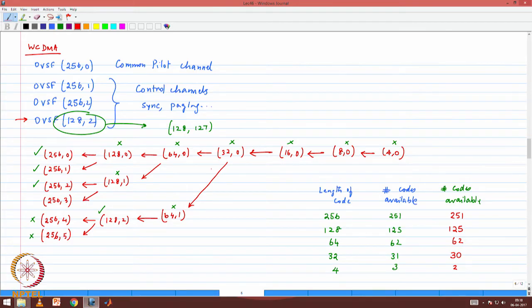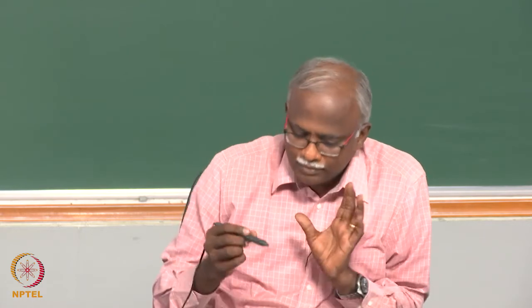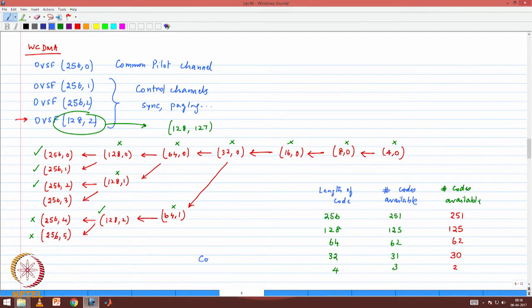And so it does not affect the number of successors, but it affects the number of earlier codes or predecessor codes. And this is an indication that if you don't do your code assignment properly, you actually can affect your capacity. So there is some concept or understanding of something called code reassignment. Okay, for optimization of the performance, you can do a code reassignment and say, okay, no, instead of using spreading factor code number 127, start using code number 2.